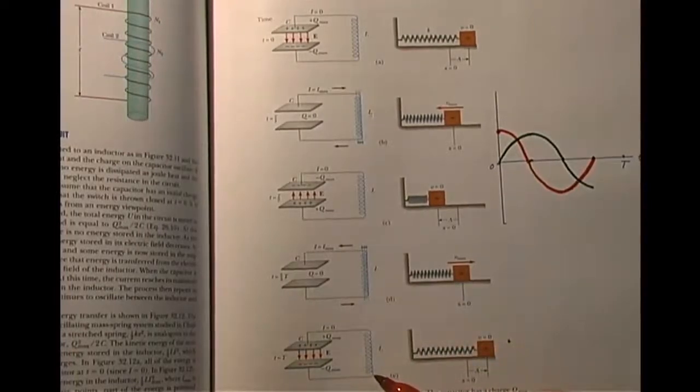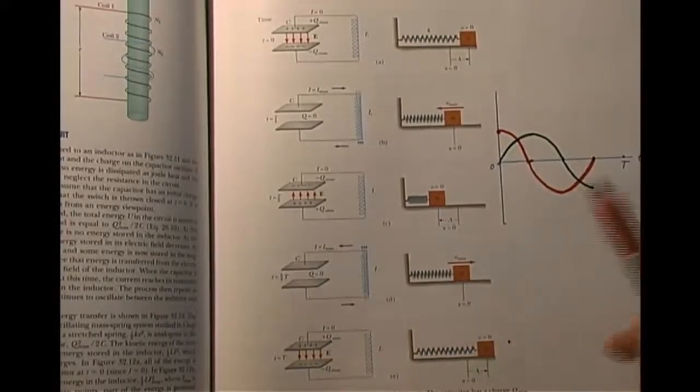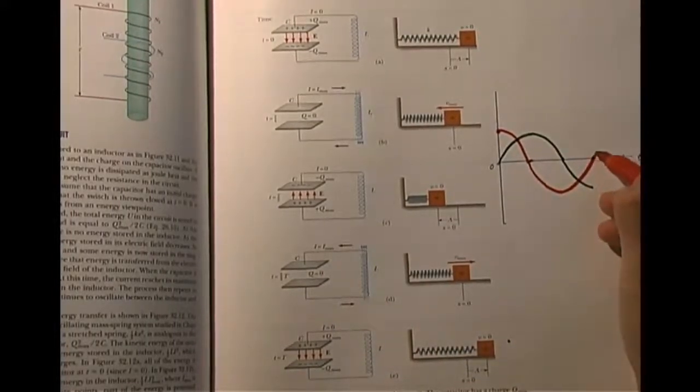After a quarter of a cycle, you have again established a maximum amount of positive charge here and a maximum amount of negative charge here. This is when again all the energy becomes electrical, no magnetic energy, or no current, just like here, no velocity. As far as the charge is concerned, you start from 0 value here, and you gradually go back to a maximum, like this.